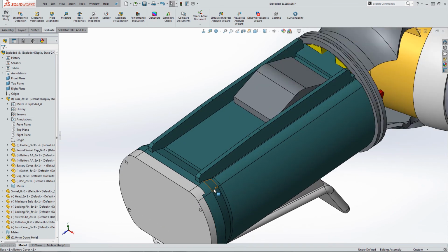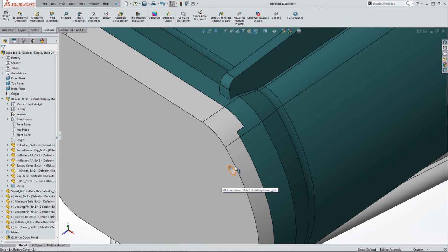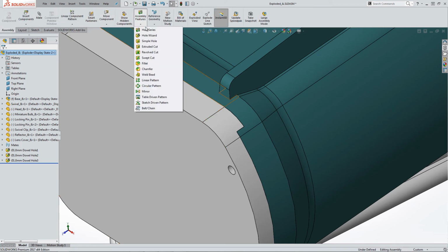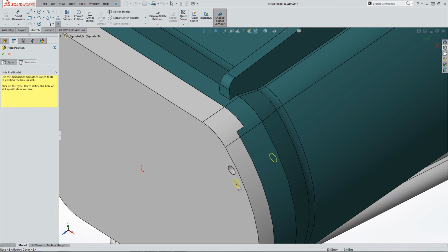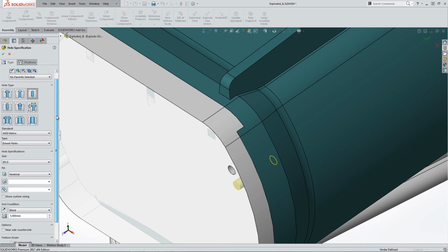So in this case, if I wanted to add in a hole and propagate it through, I have this hole that was misaligned, right? We determined that this hole was a misaligned hole. So let me go into my assembly features and throw in a Hole Wizard hole. It doesn't really matter specifically what it is. All right, the depth is fine, the size is fine.